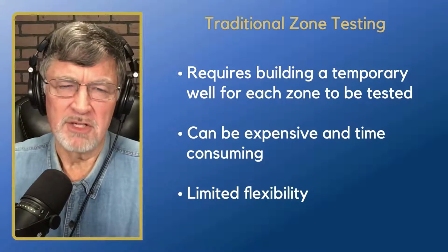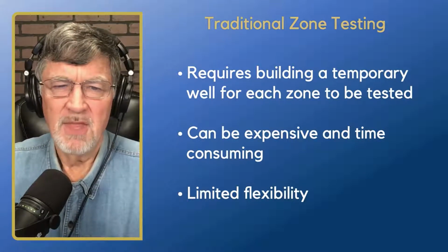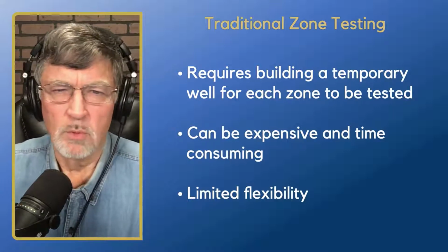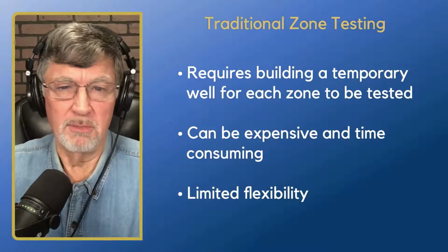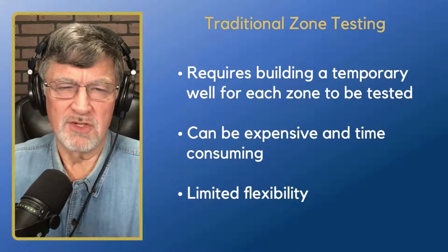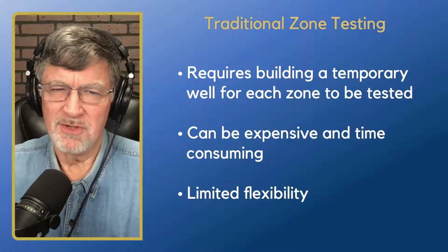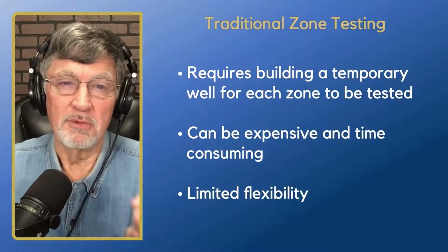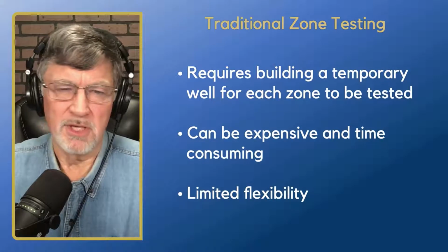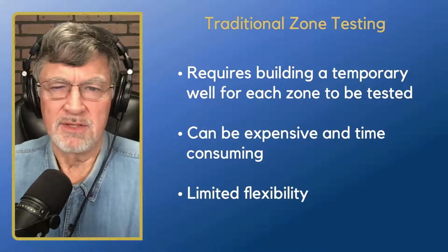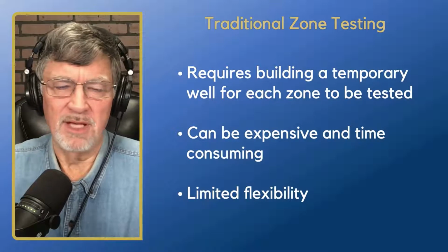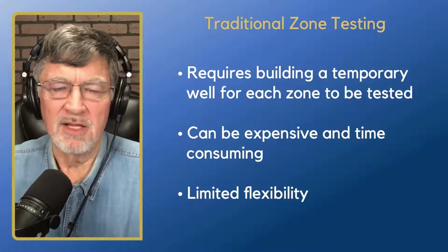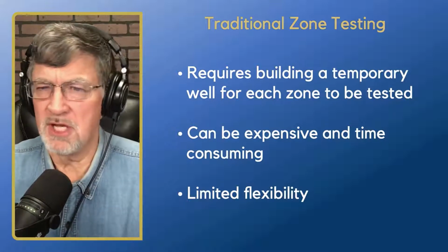And then we have limited flexibility with this. Obviously, you don't get the granularity that you might with well profiling, and we'll look and see what that looks like here in a little bit. So you're really testing broader zones, usually 20 to 30 feet at a time. And so you're not able to get that really granular look-see at things and really subdivide some of those zones. Otherwise it would be hideously expensive. So limited flexibility, which means that you may not dial in your well design exactly right because you're testing some wider zones there.